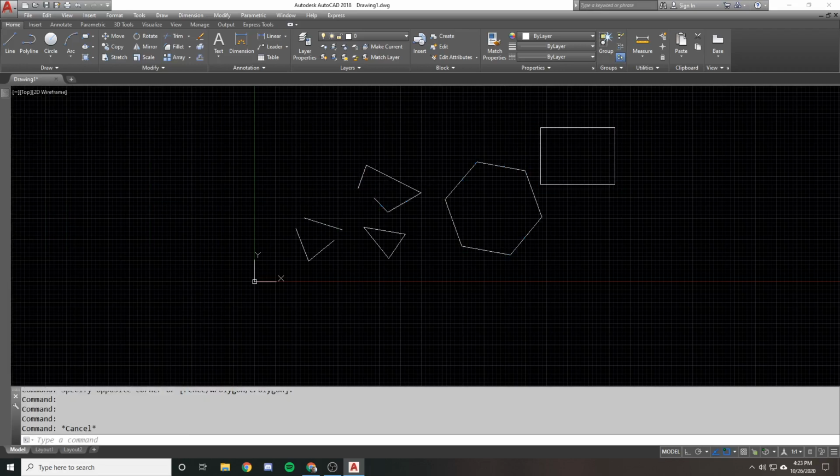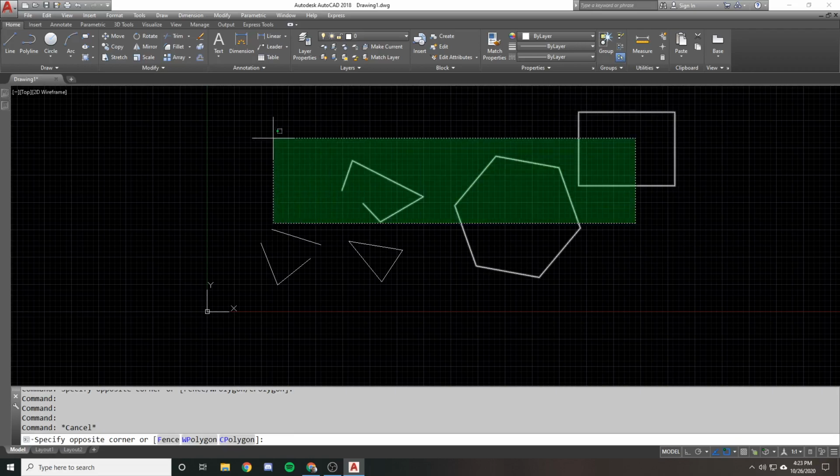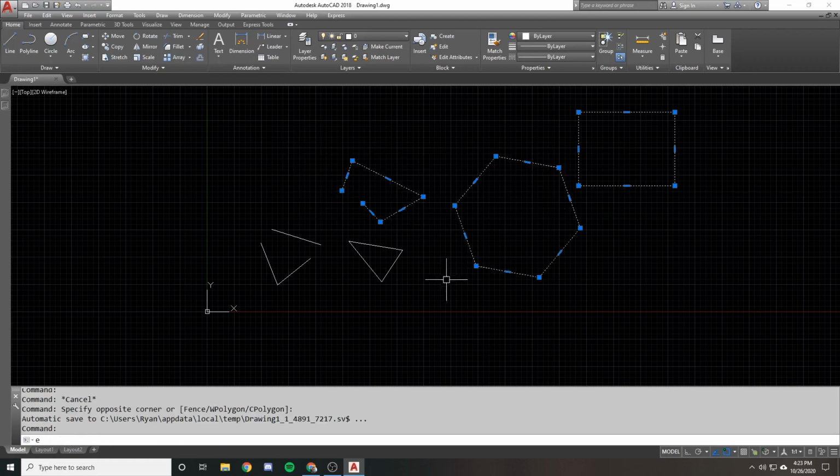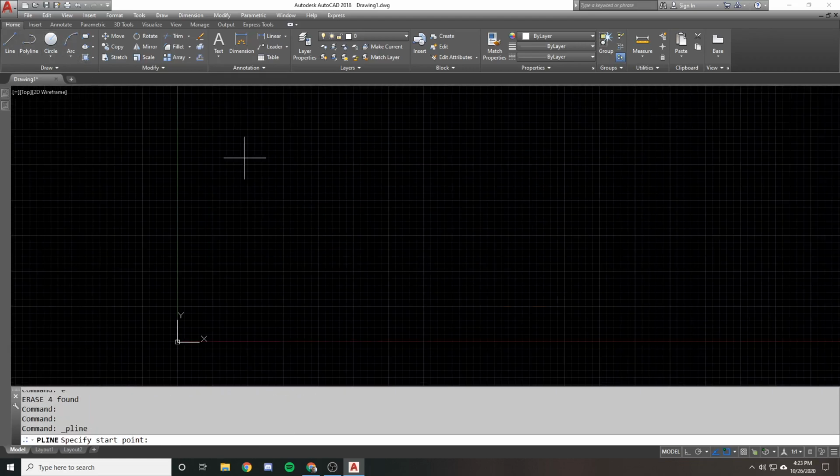So, all right, let's get into the options of what you can do with a polyline when you start creating it. So you know how you can create some quick polylines, whether they're open-ended, whether through the polygon tool or the rectangle tool. That's how you can create polygons. Let's start looking at some of the options. So we initiate our polyline command. We pick a start point. You have a few things you can do. You have arc, half width, length, undo, and width.